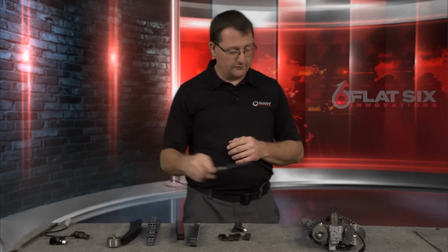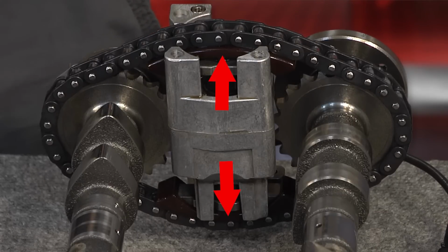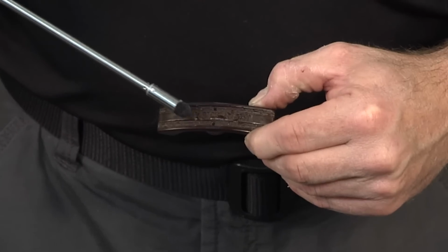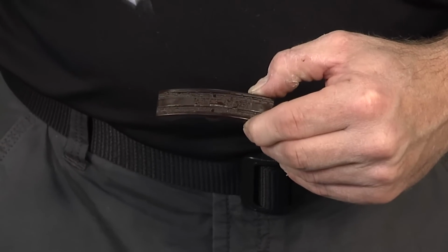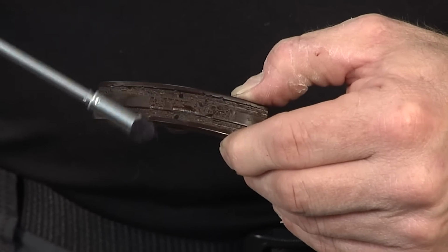But now, the most important thing, and the thing that has brought almost all of you to this video with high camshaft deviation values from your 5-chain engine, are these particular wear pads located here and here on the camshaft adjuster of only the 5-chain engines. These things wear, and they cause big camshaft deviations that are causing big problems for engines. This is fairly simple to address, and we're going to go over what these deviations are and some of the things you need to do before you jump into repairing an engine that has worn chain guides.